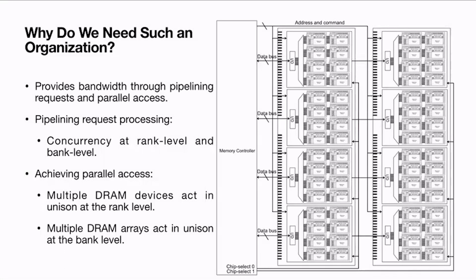And not only this, but there are also many timing constraints the DIMM has to follow, and these timing constraints are again provided by the memory controller. That means when I give a command, I cannot give the next command without waiting for some amount of time. So those things will also be provided. We'll discuss that in the coming slides.